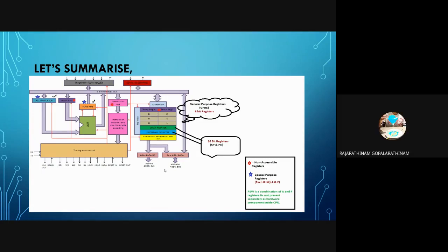Lower byte is 00, higher byte is 20, and each is also going to have an address. So I have fetched the opcode first, right? Only 1 byte can be fetched at a time, because the data bus is only 8-bit. So obviously I cannot fetch all 3 at once. If PC is going to be incremented by 3, then how will I fetch my other 2 bytes?